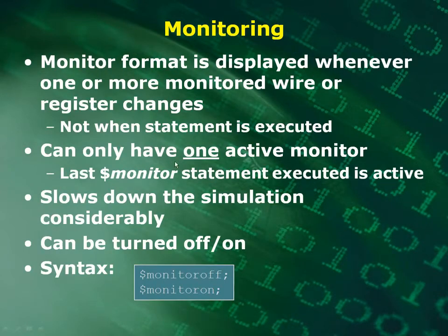You can only have one active monitor, so the last $monitor statement executed is the one that's active. The thing to remember about using this $monitor task is it'll slow down your simulation quite a bit, but you can turn it on and off by using these statements.